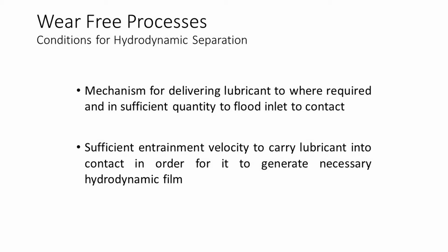If all types of tribological contact operated with hydrodynamic or elasto-hydrodynamic lubrication, then we would not have any problem with wear. We would need little in terms of lubricant additive chemistry, other than the provision of additives to provide oxidation and shear stability, and we could use any moderately viscous fluid. If this were the case, we could lubricate our systems with glycerine instead of oil. This is clearly not the case.